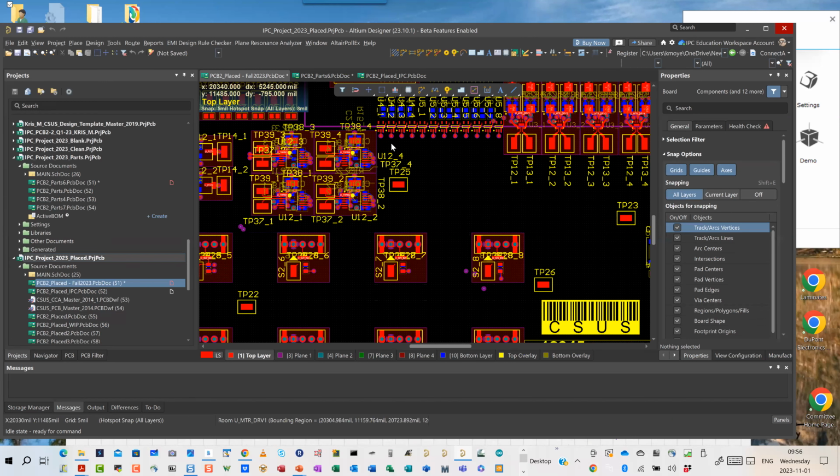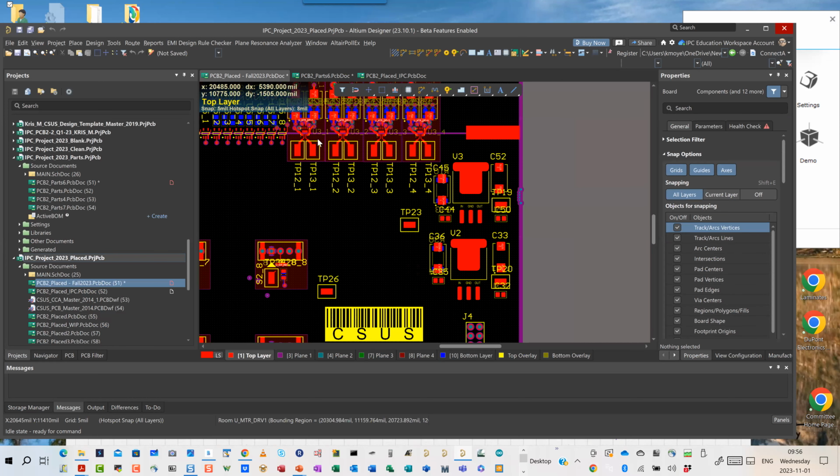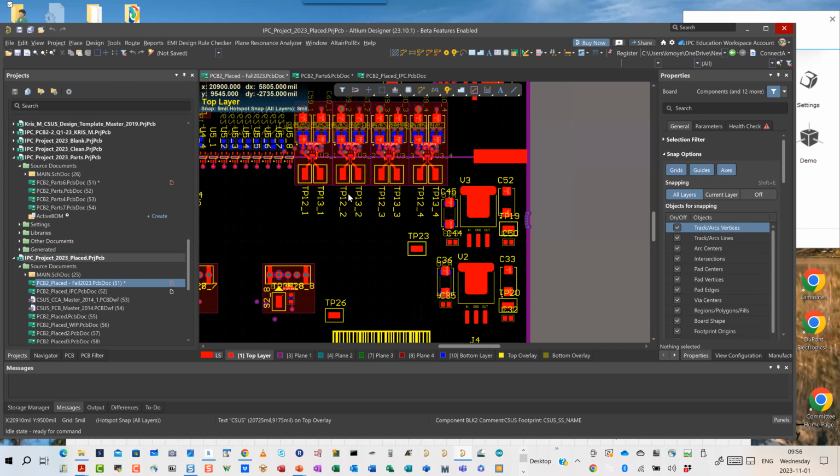So the input pin is over here on the analog side and the output signal is over here on the digital side. Same thing with the motor drivers, right? In my picture, I originally just had the motor drivers down here in a block, but I realized it's the same thing. The input side of the motor drivers needs to reference the digital side, so I can find a way to have them straddle using a combination of rotation and parts placement that we talked about in week 2.